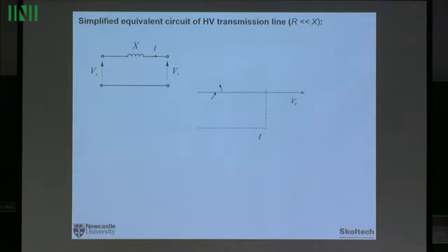The most simplified model is for the modeling of the transmission line. We just assume that the only thing relevant is reactance, because it's about 5 to 10 times bigger than the resistance, so we forget the resistive effects. It means we do not model transmission losses. So this is approximate analysis. From my point of view, it's useful in order to understand, because that allows you to derive some equations and get a better understanding. But it's not near exact modeling.